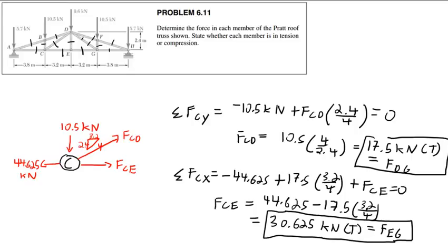I would shy away from using those. I'm more familiar and more confident using the combined equation m plus r is less than or equal to 2j to determine whether a truss is statically determinate. I'm just looking for loops to make sure I got all the solutions. Well, what do you mean by number of solutions? You probably mean the force in each member, right?